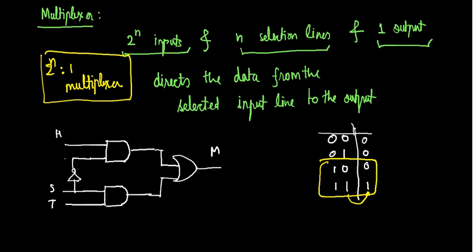For 0, I may say that you give me data. For 1, I can say that you give me data. The other person. Say, for example, you have 8 such friends. Can you tell me how many selection lines you require? Now for 8 such inputs, 3 bits are sufficient to have those combinations such that I can receive the data from all 8 of them.